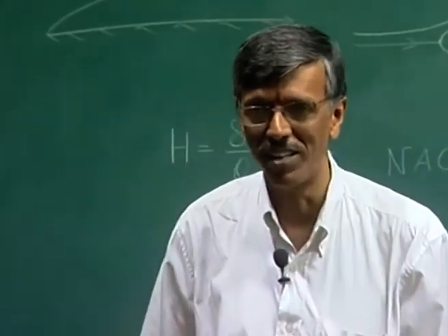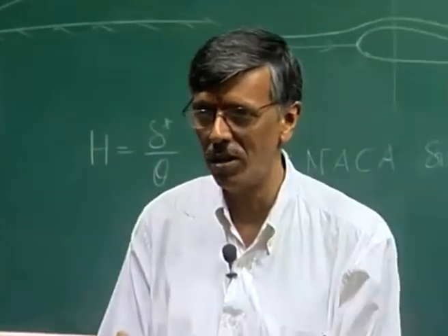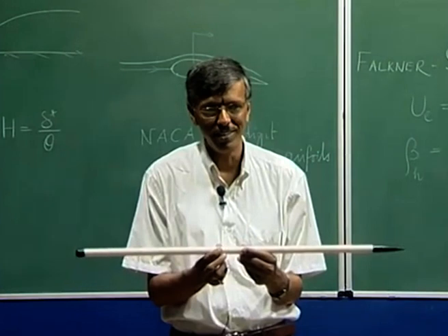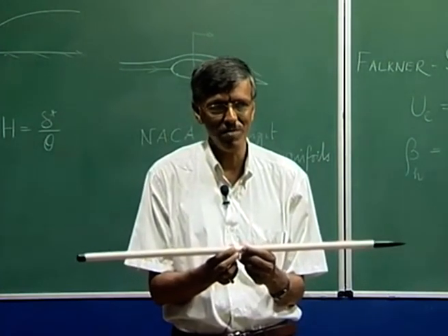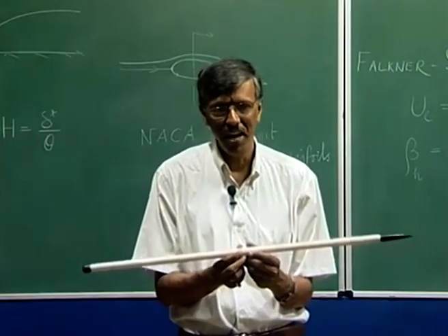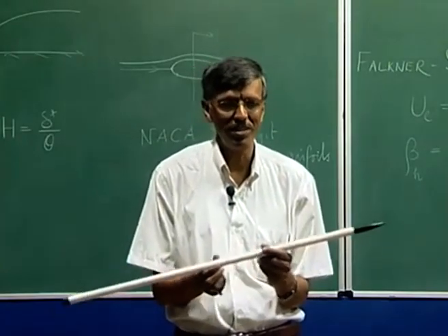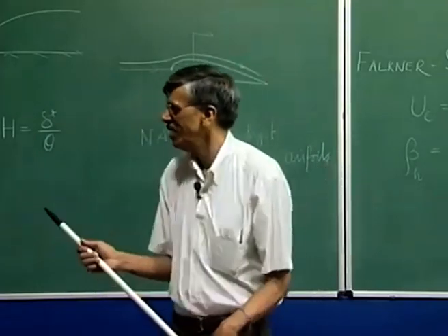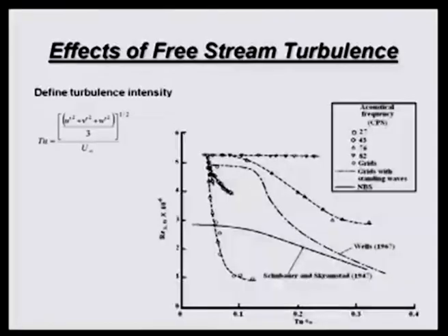But in the same tunnel we did experiments with flow past a cylinder of 2 different diameters. To keep the Reynolds number the same, we had to change the speed for the different diameter, and what we saw is a totally different footprint of transition. We will come to that. Nonetheless, historically people have gone through it, and let us show you what we get.